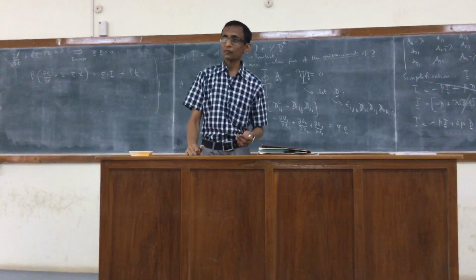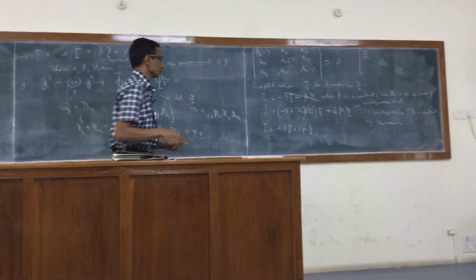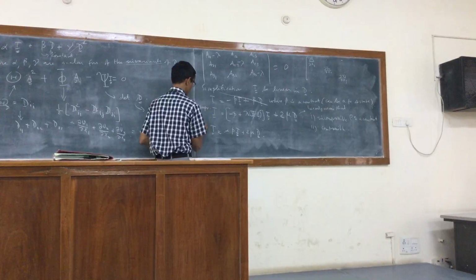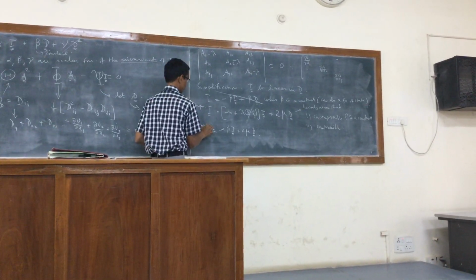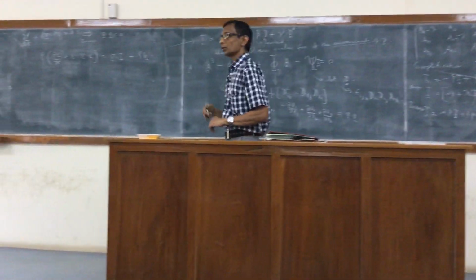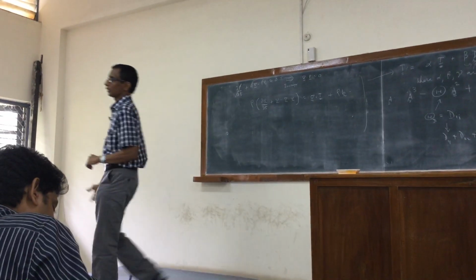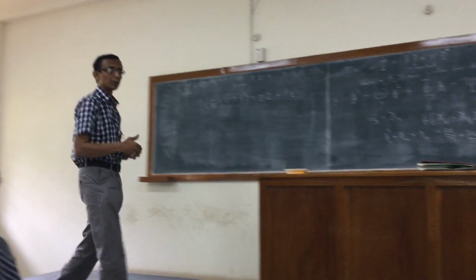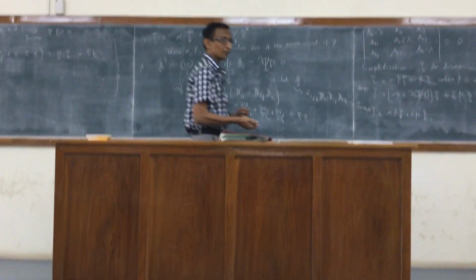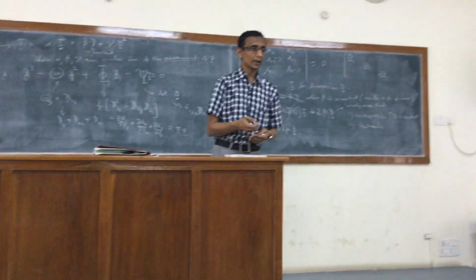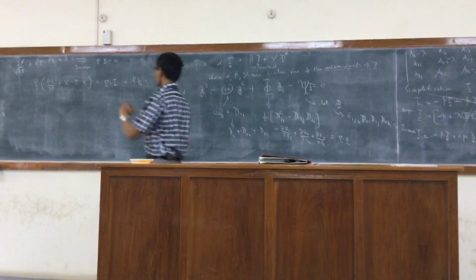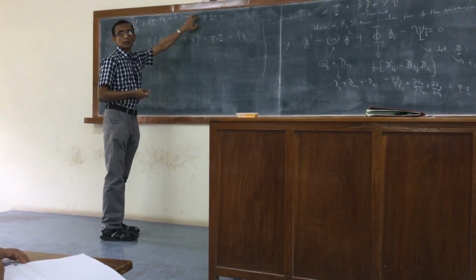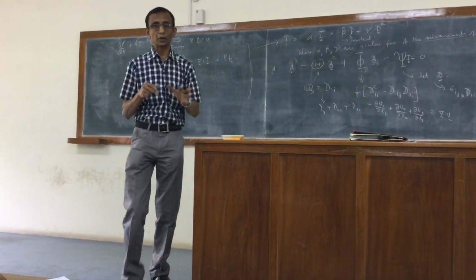Now for a compressible fluid, right? So this I can retain for a compressible linearly viscous fluid. Although it appears that the equation for the incompressible fluid can be obtained from that of the compressible fluid by simply taking the divergence of the velocity field to be 0, which is what it is, there is an important difference. If you look at the equations for the incompressible fluid, the density is no longer a variable of the motion.